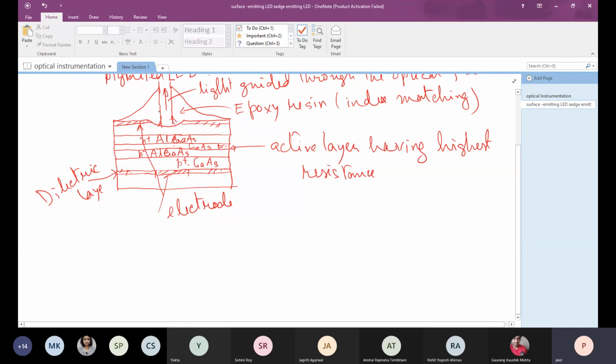If two mediums, one having the guided property, another having non-guided property, are very close to each other, then light tends to be coupled to the guided zone for a certain length, and thereafter, of course, it tends to come out again. So this resin layer has to be narrowed down within a very small distance, maybe a fraction of a millimeter or at least 1 millimeter or so.